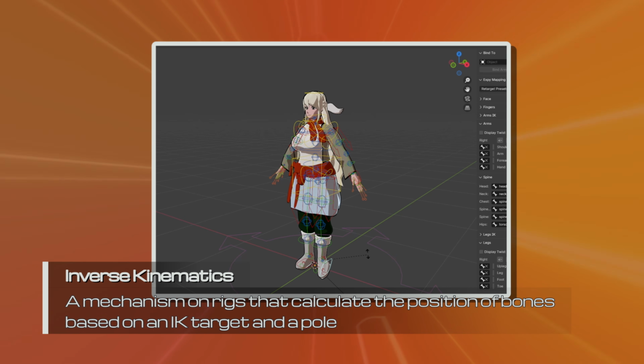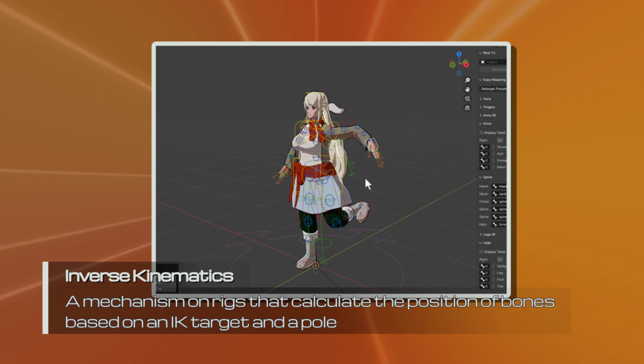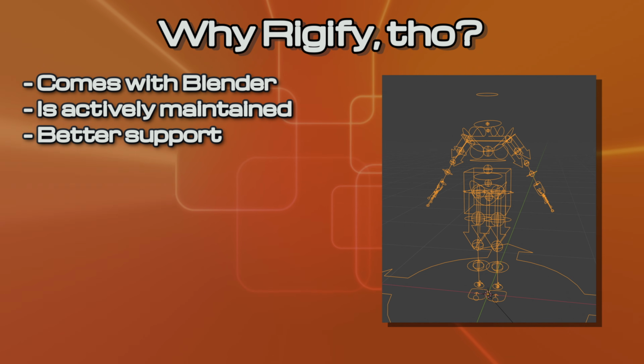A remedy that advanced rigs like Rigify provide for this is called inverse kinematics, or IK bones. Rather than moving each joint on the arm, you can move the hand IK bone and the rest of the arm will point toward it. It saves a ton of time. There are other rigging tools out there, but I chose Rigify because it comes with Blender, is actively maintained, and it's much easier to get support.